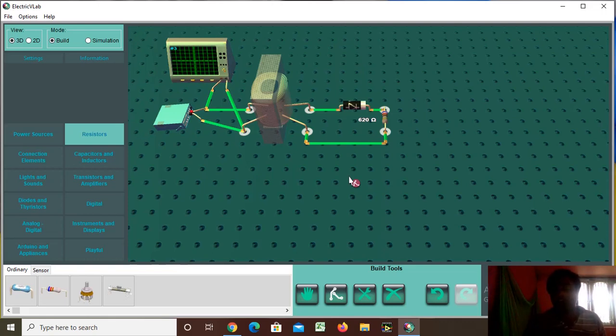You all know the relationship between voltage and turns ratio: V2 divided by V1 is equal to N2 divided by N1. In other words, V2 divided by V1 is equal to N. Here we don't know N1 and N2, so I can write the formula like this: V2 by V1 is equal to N. Now V2 I need 12, divided by the input V1, which is 230. Let's divide, and you will get the turns ratio.